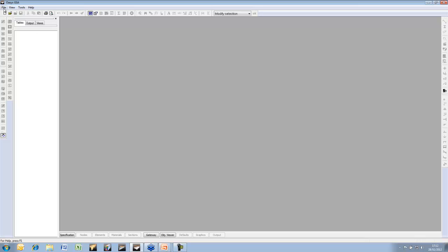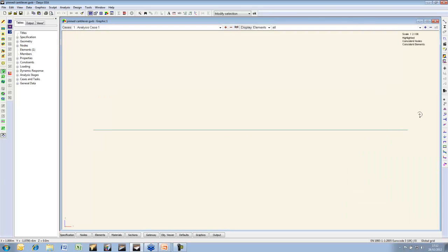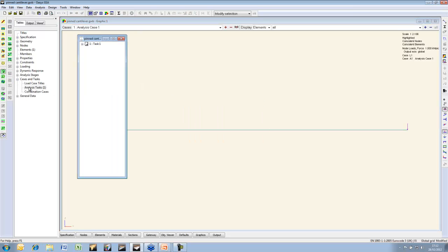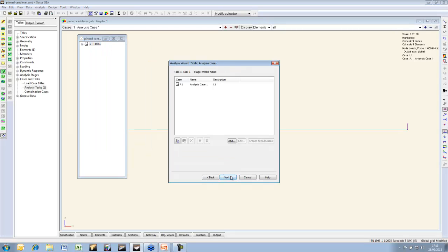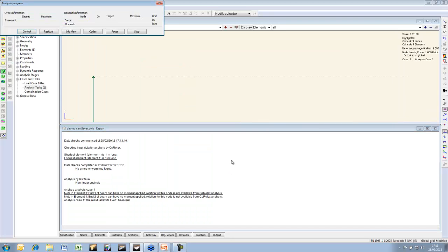Now, talk about deflections. You can deal with some quite seriously large deflections. I mean, here we have a cantilever, but this cantilever is pinned at one end. Now, again, standard linear analysis and a lot of non-linear analysis from other programs won't be able to cope with this, but with GSA methods, it can. Let me just run through, make sure deformation set to 1, and analyze that.